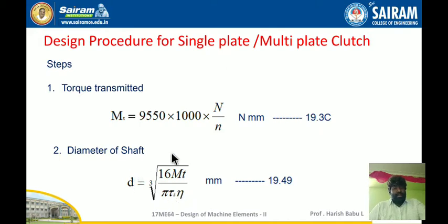This diameter of the shaft is calculated when d1 and d2 are both unknown. The shear stress can be calculated using the ultimate stress, that is the yield stress. From the yield stress you are going to calculate the stress, from the stress you are going to calculate the shear stress, and the keyway factor you can get from the table.